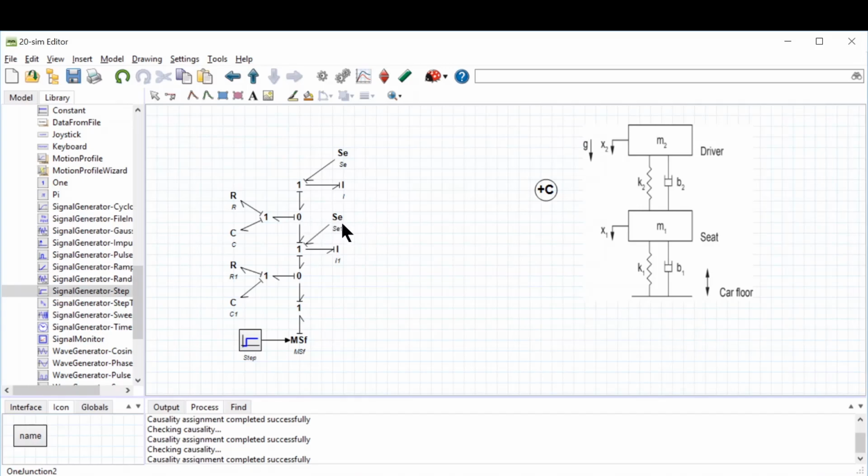as I explained in the text. Now, if this one minus this one wants to be positive, which is the displacement of the spring here, therefore this flow should be larger than this, meaning that the displacement or velocity of mass 2 should be larger than mass 1. That means that it puts the spring under compression, and that is exactly what I want.